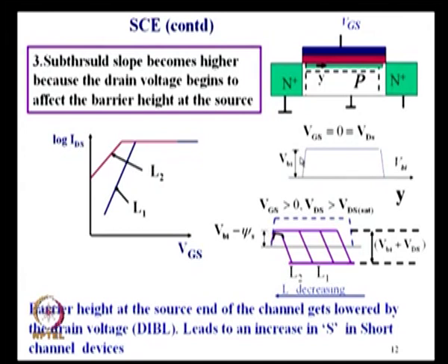It gets reduced, because plus voltage applied, plus minus, plus minus. So, this gets forward biased. So, VBI gets reduced. If the depletion layer width is only here, the first curve here, you will have a reduced barrier height from VBI by psi s, flat there and going like this. So, this barrier height reduction is completely controlled by the gate.